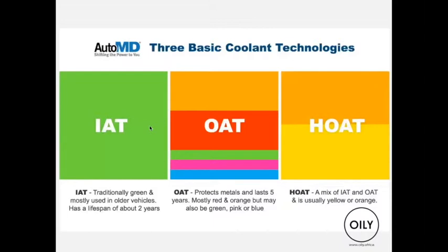Okay, now there are three basic coolant technologies. There's the CAT, or common antifreeze technology. Traditionally, it's green in color. It's dyed green, and it has a lifespan of about 2 years.